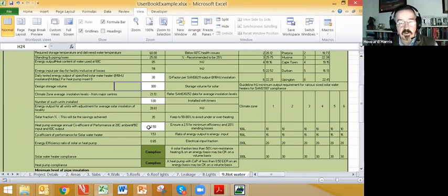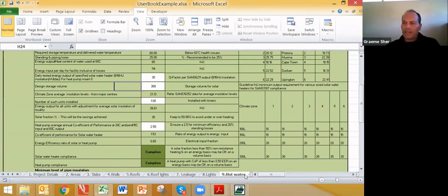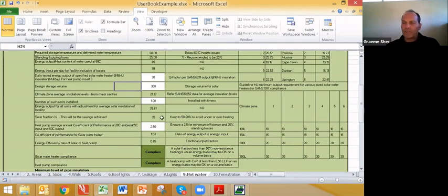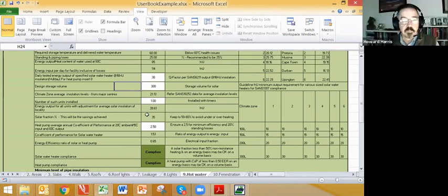Graham, any more comments on the hot water from you there? I think it's important to remember that one shouldn't really go for the absolute minimum in terms of the current legislation. You do want to have as much water storage as possible to cater for morning ablutions, considering there's no sunlight in the nighttime. And so you do want to have about a 300 liter system for a 3-bedroom house, at least. Yeah. Good. All right, the next tab is,